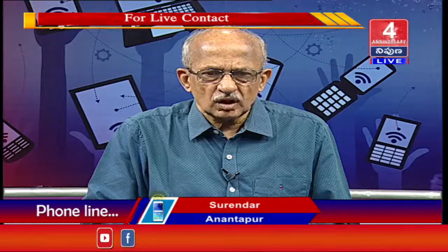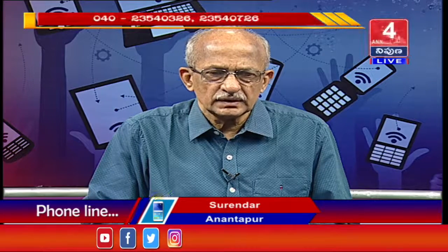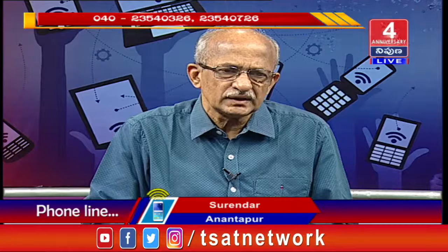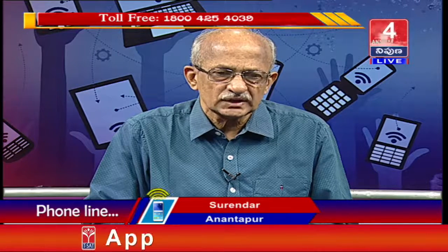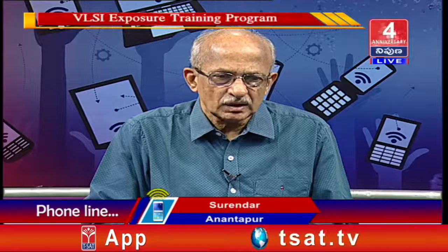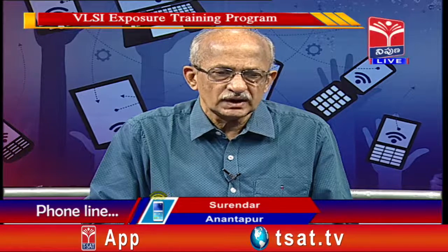Because MOS, metal oxide semiconductor, why are we using CMOS? One of the main advantages is basically the density. Density can be extremely large for devices. The second thing is that the power consumption, compared to bipolar devices, is much lower in CMOS devices. Why do you use PMOS and NMOS? I will answer this question shortly. Why not only NMOS or why not only PMOS? Okay?